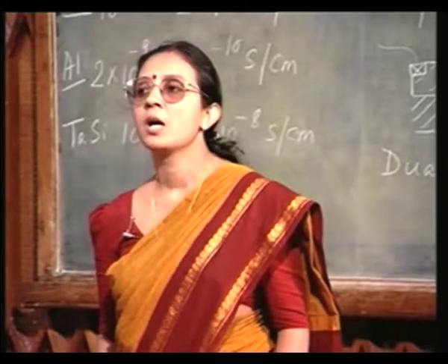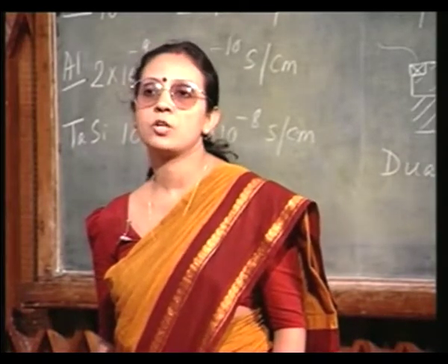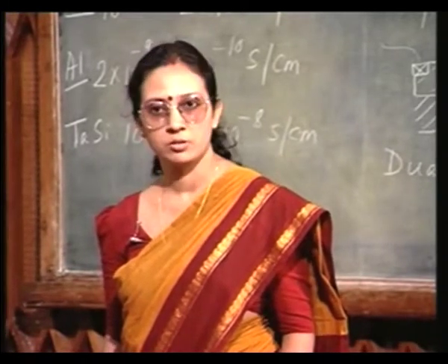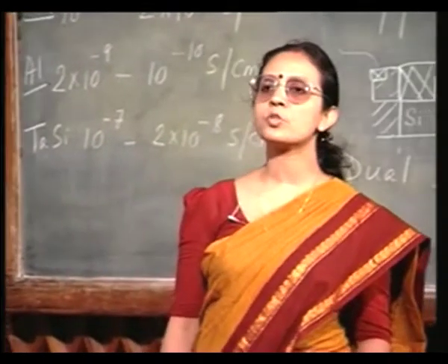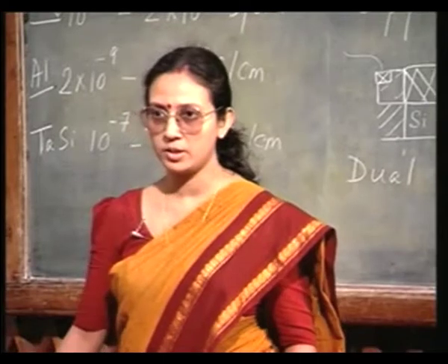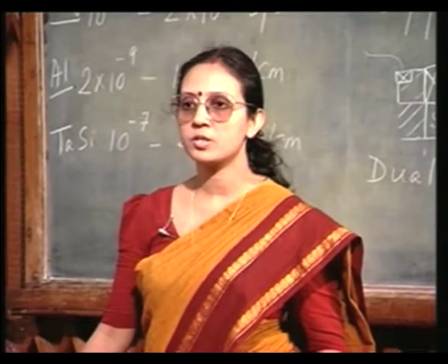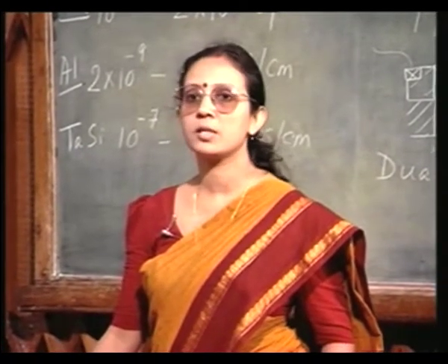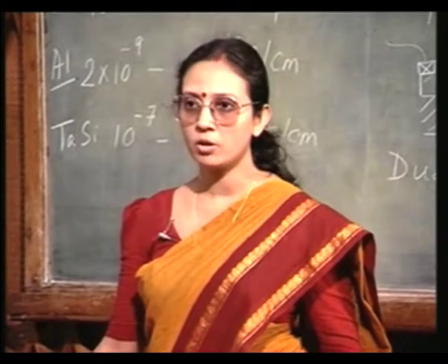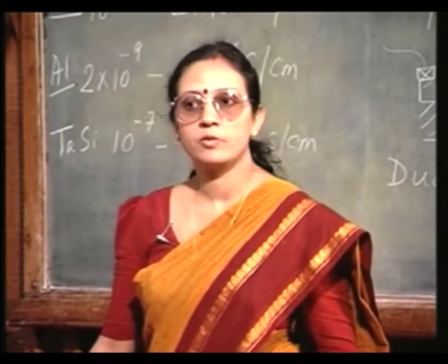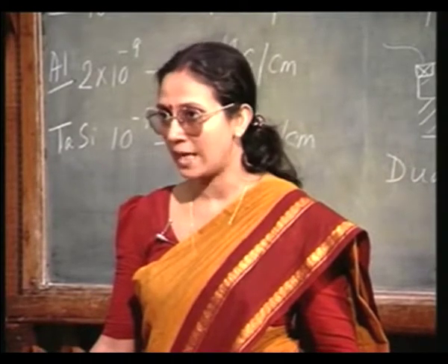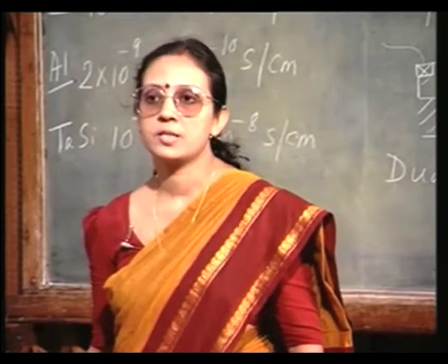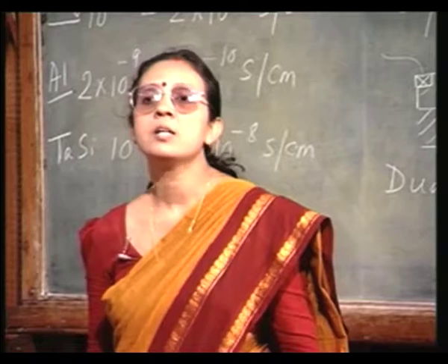At the same time, the polysilicon gate technology is well researched. We have a wealth of information about the polysilicon deposition. And since remember, gate is the most vital part in the MOSFET technology, you would like to retain all the positive features of the developed technology. That is, you know exactly what the polysilicon deposition conditions should be in order to guarantee optimal performance of your device. So, you do not want to disturb that. What one is going to do is, on top of this polysilicon gate, we can deposit a silicide.